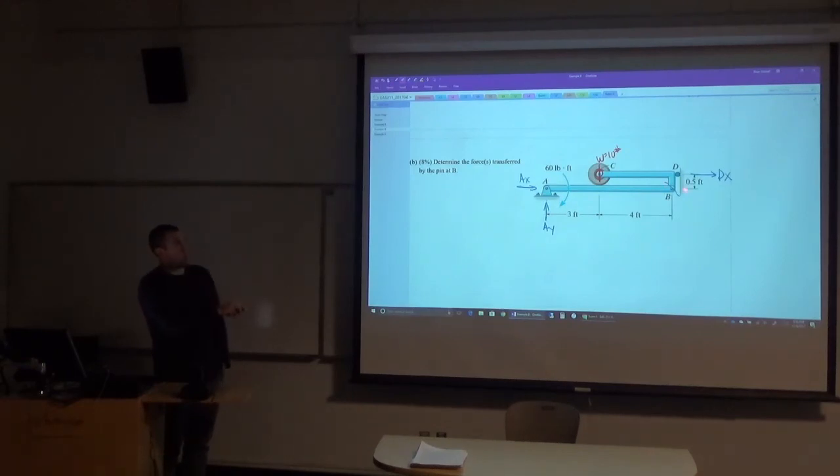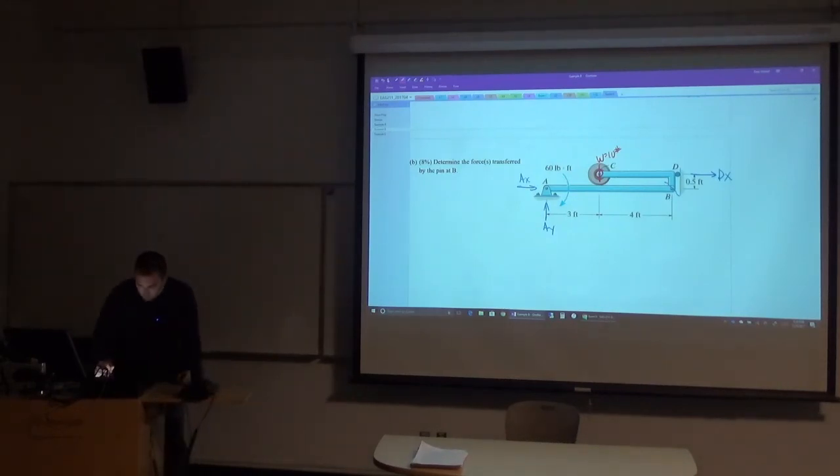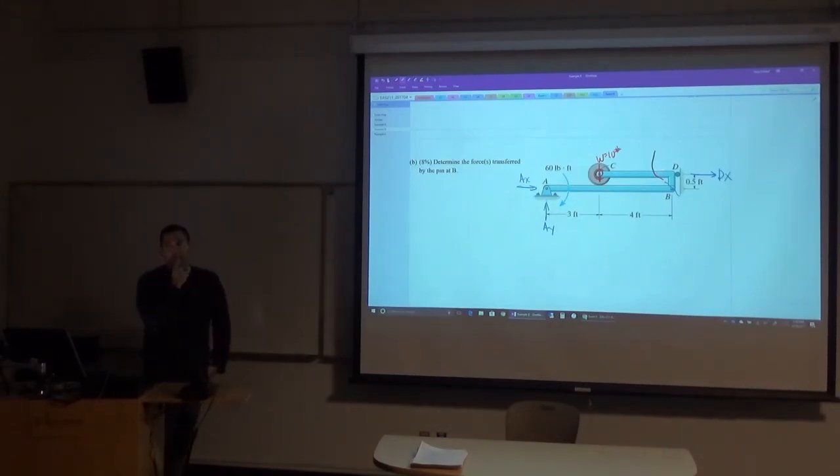Well, we need to finish our section cut basically. So if you're telling me I get 2 unknowns from this part of the section cut, I've got to continue that on and completely separate and have 2 different sides of my section cut. So do I want to continue my section cut like that? What happens if I were to cut through this member CD? How many unknowns am I going to get if I make a cut through CD? I'll get 3. So then I get 3 up here, I get 2 down there. That's going to be 5. That's not going to work.